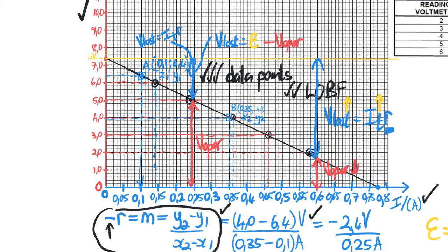So even though on the surface this graph doesn't look like it includes Ohm's law, embedded in it, behind what you're seeing, is in actual fact Ohm's law. And that's Ohm's law being applied internally in the battery. And so some teachers actually label this as V internal, which means the voltage loss inside the battery.